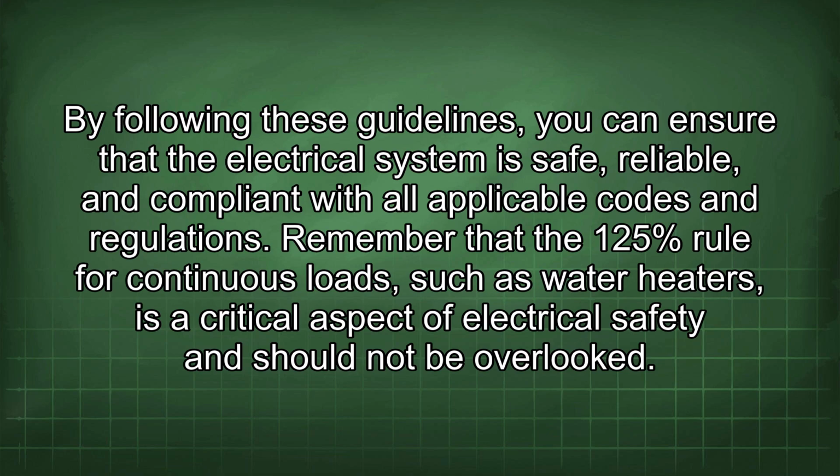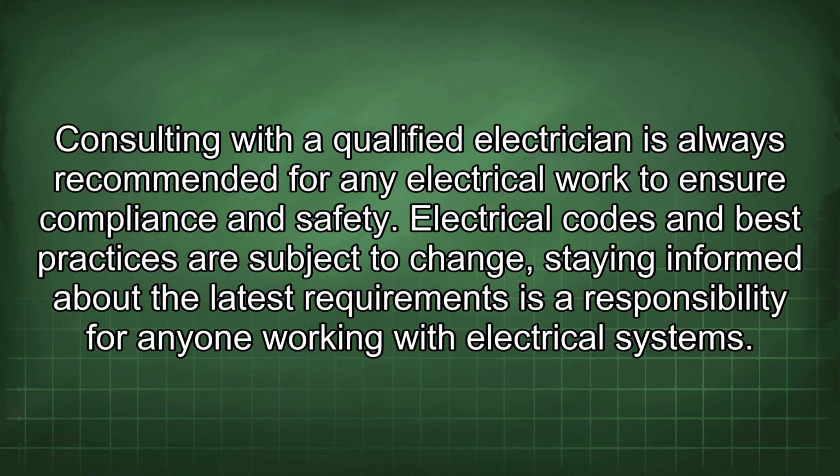Remember that the 125% rule for continuous loads, such as water heaters, is a critical aspect of electrical safety and should not be overlooked. Consulting with a qualified electrician is always recommended for any electrical work to ensure compliance and safety. Electrical codes and best practices are subject to change. Staying informed about the latest requirements is a responsibility for anyone working with electrical systems.